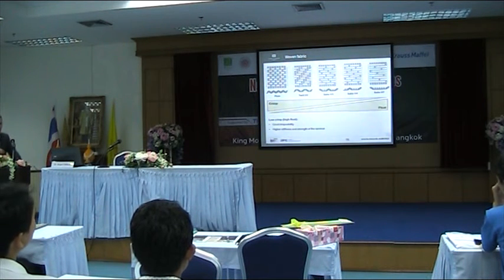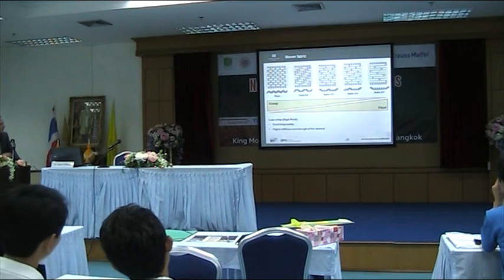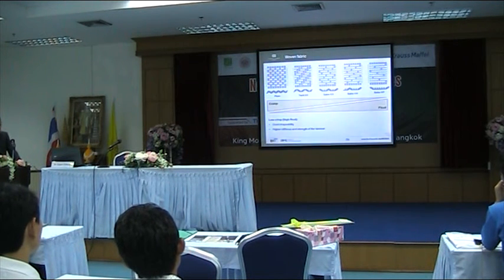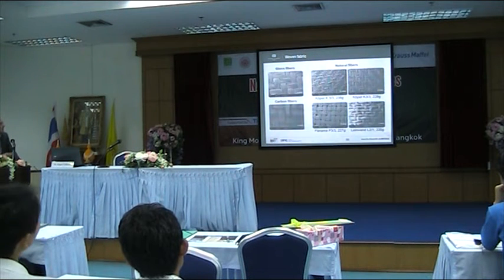So you can much more have a better drapability for complex shaped parts, for example. So a lower crimp means, of course, good drapability and higher stiffness and strength of the laminate, because the fibers are straight, more aligned than here. Because here you have a reinforcement also in Z direction, not only in plane direction. So this is typical.